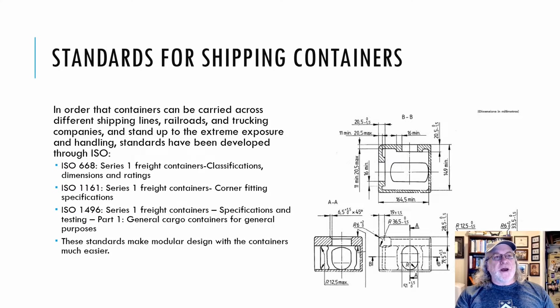Now going back to this one right here, we can't use these loads. I was told I was arrogant by somebody on the internet because I didn't use these loads, but no, it's not arrogance. Once you start cutting up a shipping container, you change the strength of it. You can't go on the loads that come up in the specifications, even if it does seem kind of arrogant. You have to run the analysis.